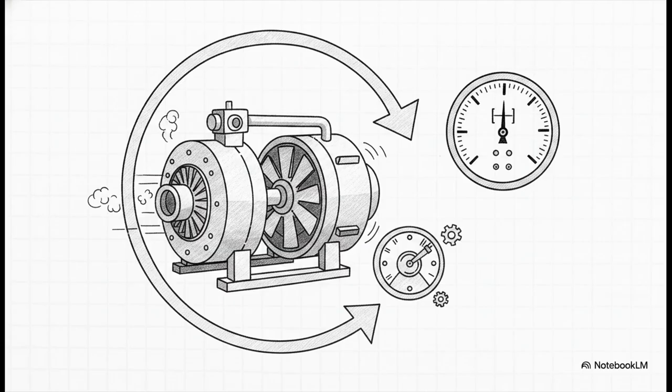But let's flip this scenario entirely. What if you're controlling a fast, dynamic offshore gas compressor? This isn't a slow tank of warm water. We're talking about highly volatile equipment where pressure ratios change in literal milliseconds. Here, closed-loop modulating control is absolutely required. An anti-surge valve has to continuously creep and adjust, reading flow and pressure to stay off the surge line. A wide tolerance or a lurching on-off action here wouldn't just be inefficient, it would be utterly catastrophic.